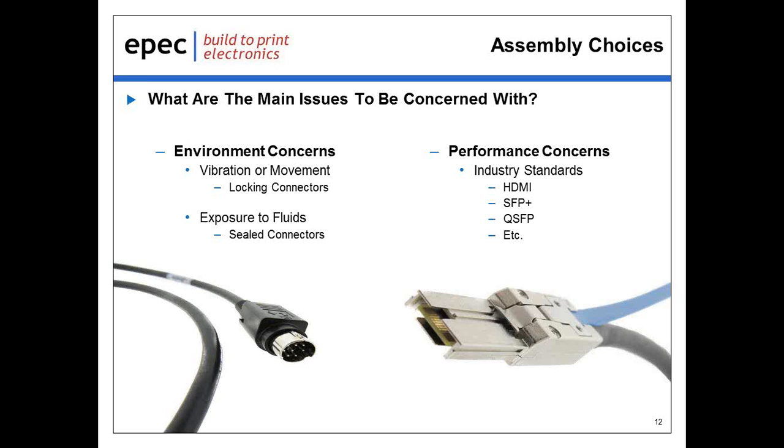For some installations, the performance of the assembly is going to be determined by industry standards. These standards will really dictate that certain connectors be used to meet specific footprints for mating, as well as signal integrity. Standards such as HDMI, SFP+, QSFP, USB, and a host of others really do determine what design and what performance the connector has to perform to.